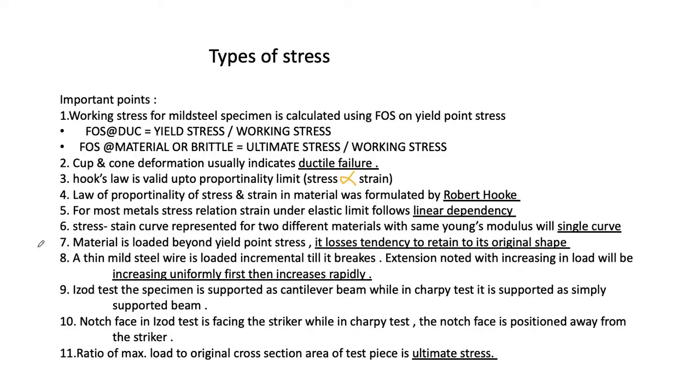A thin mild steel wire is loaded incrementally till it breaks. Extension with increasing load will increase uniformly at first, then increase rapidly. In the Izod test, the specimen is supported as a cantilever beam, while in the Charpy test it is supported as a simply supported beam. These are important points mainly asked in competitive exams. In the Izod test the notch face is facing the striker, while in the Charpy test the notch face is positioned away from the striker.